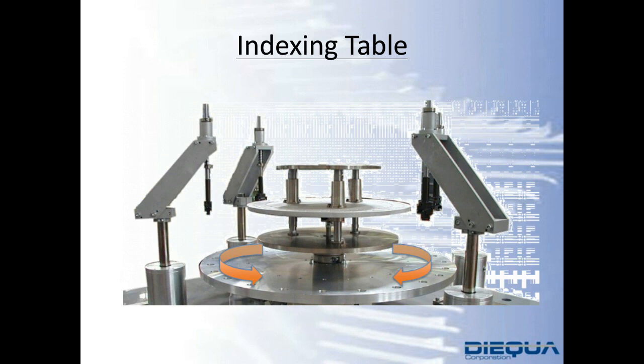In most catalogs, you'll see axial or radial capacities. All these values are indicated on the output shaft of a gearbox, right? Whether you're pushing the shaft in or out of the gearbox, or pushing at maybe a halfway point on the output shaft. But in order to calculate this type of influence, you should consider that this is a tilting capacity. You have, in essence, that force represented in a bending capacity, so that's where a robot flange would be better suited.